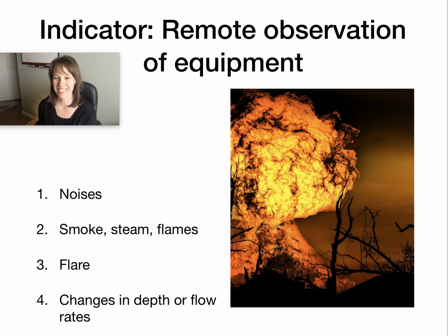Of course, this is like a major problem, but there could just be an issue where you look out or you drive up for your shift and the flare's going like crazy, and you know that they've had a system upset or something different is happening. If you're at a water treatment plant, you may see a change in the depth or flow rates through the channels or different reaction chambers, and that would also give you an indication of a problem in the system.